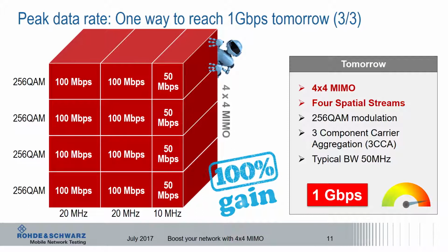We need 4 receive antennas in smartphones on all bands here. Sufficient multipath with similar strength and a high signal to noise and interference ratio. So let's include some sense of reality. 4x4 MIMO with more than 2 carriers is not yet supported by the chipsets. So this is really a limitation of the chipset, although they support today 4 carrier aggregation with 20 megahertz and 2x2 MIMO.